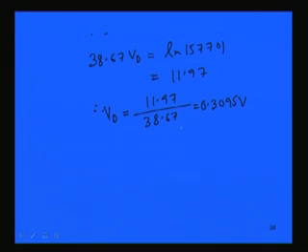Now, just notice that for 0.3095 volt we get 100 milliampere, but earlier for 1 milliampere we had to apply a voltage of 0.19 volt. So, even if we increase the voltage by less than twice, we are getting 100 times the diode current. For a small change of applied voltage, we get such a huge rise in current, and that is very clear from the characteristic curve also.